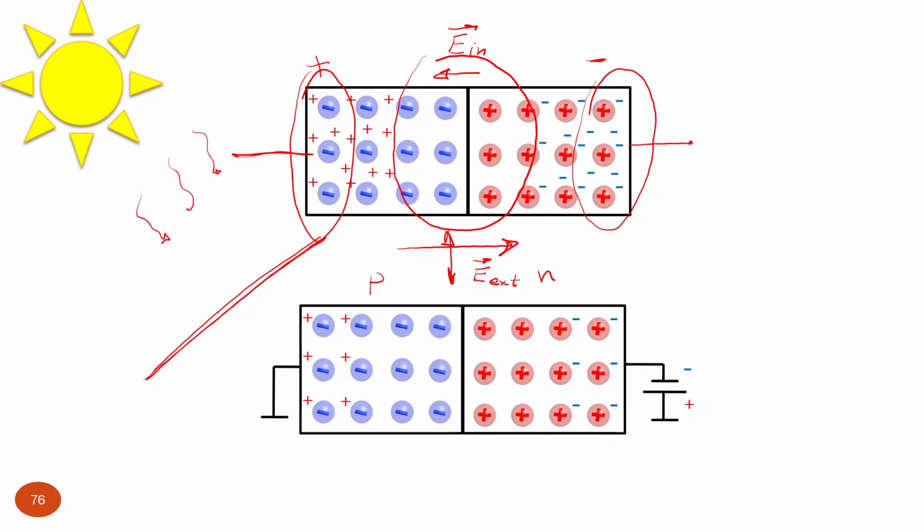So from both sides we create conditions by this photoactivation, when we increase both drift and diffusion current, drift of minority non-equilibrium and diffusion of majority equilibrium charge carriers, and they still compensate each other.